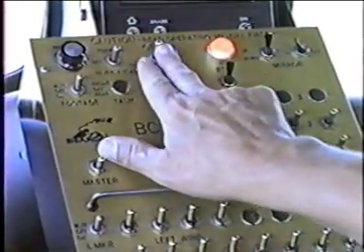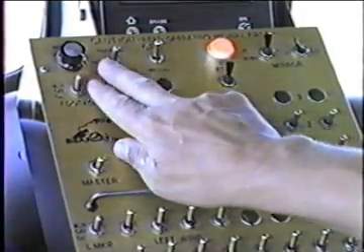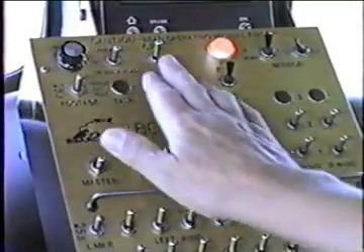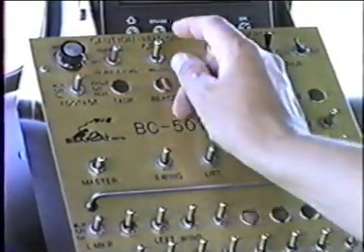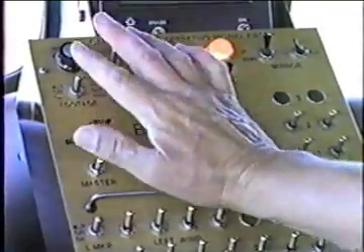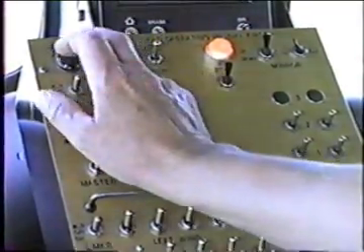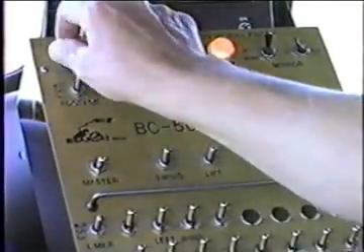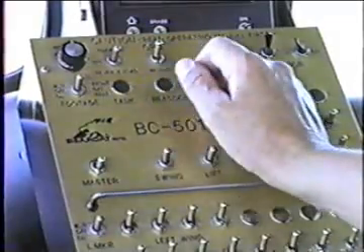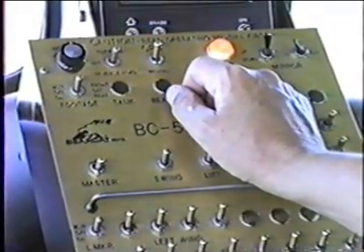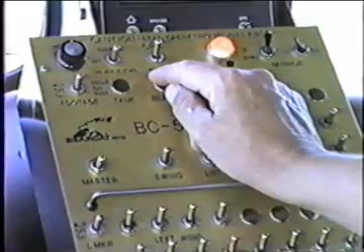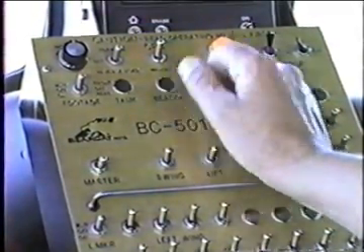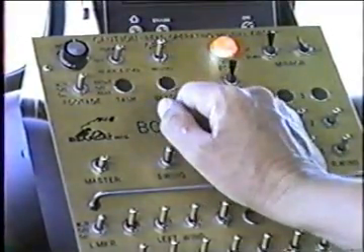If we're in CRC, then the computer totally manages the direction and the speed, and these two switches are phased out of it. They have no effect when it's in CRC. Normally, if you're in CRC, leave these switches in the center off position and the speed turned clear down to 0 here. The reason we leave that at 0 and the center off position is so that if we go to use the manual control from the rear of the truck, the front isn't trying to override it. Most of what we do is going to be in the CRC position.